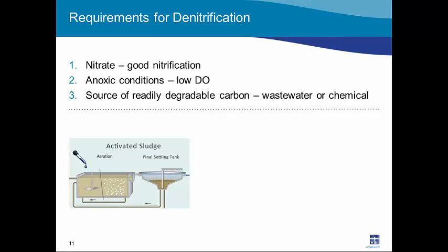Now, some water resource reclamation facilities lack sufficient carbon in their raw wastewater for various reasons. And in this case, it may be necessary for them to add synthetic carbon to the wastewater in order to drive that reaction.